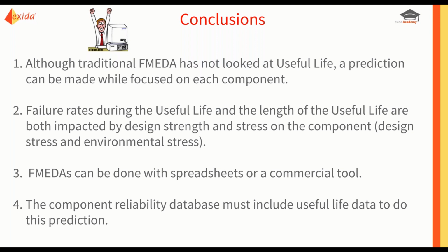FMEDAs can be done with either spreadsheets or a commercial tool. I personally like to get them done really fast, so I use the commercial tool. The component reliability database, however, to do useful life, must include the useful life data, typically as a function of design stress and environmental stress.